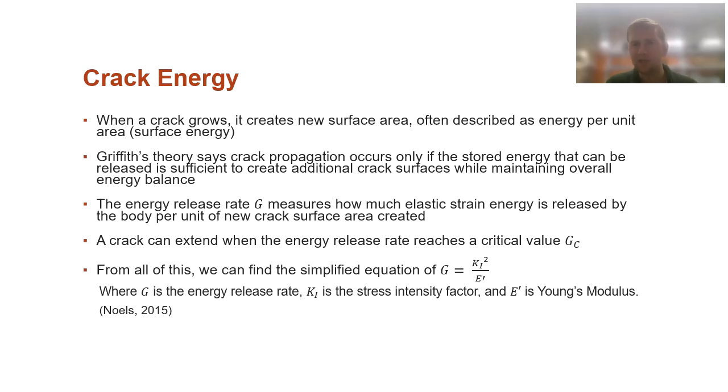So this is similar to that stress intensity and the fracture toughness that we saw, where a crack will only propagate if there's enough of a certain thing there. It's stress with stress intensity, it's energy with this crack energy. And we'll see this a lot in terms of G, the energy release rate, and the crack will propagate when it reaches that critical energy release rate, G sub C.